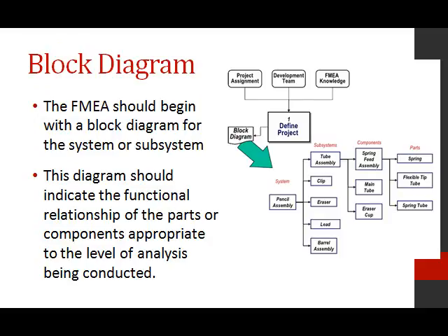The failure mode and effects analysis should begin with a block diagram for the system or subsystem. The diagram should indicate the functional relationship of the parts or components appropriate to the level of analysis being conducted.